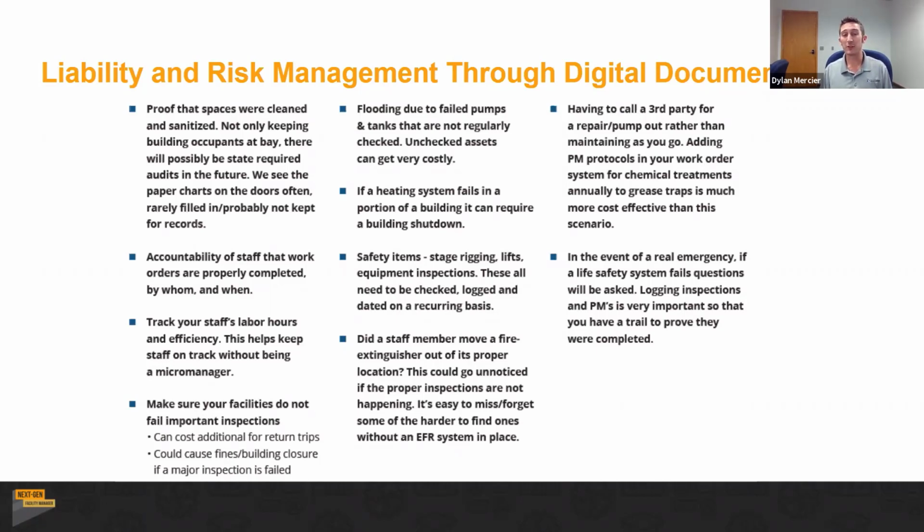Little things that could be major safety concerns that we see time and time again are fire extinguishers that get moved. Typically, they're in those closed cabinets and they have a home, it's marked, there's a sticker, but we see it often either in classrooms, mechanical spaces, stage, catwalks, things like that, where they're a little more freestanding, and sometimes they get buried with equipment. Boxes of material may be blocking it. Stored items may prevent those cabinets from being opened. And making sure all those are getting caught on your walkarounds is very important.